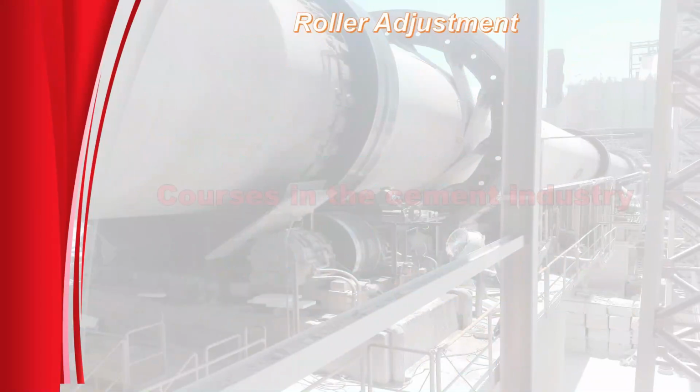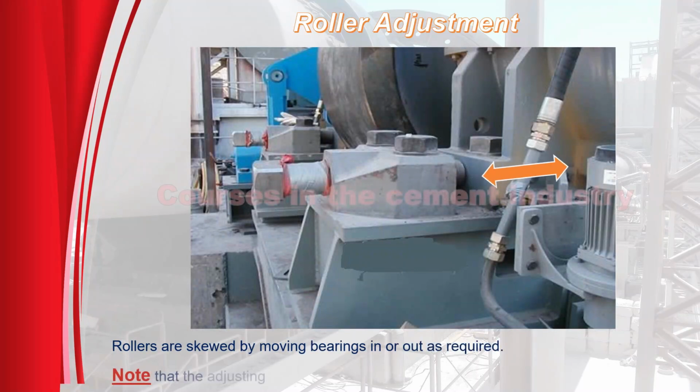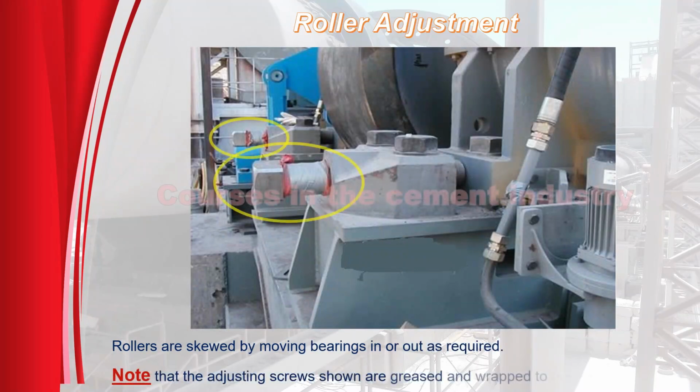Roller adjustment. Let's start important steps and notes for roller adjustment. As shown in this figure, rollers are skewed by moving bearings in or out as required. Note that the adjusting screws shown are greased and wrapped to prevent corrosion.